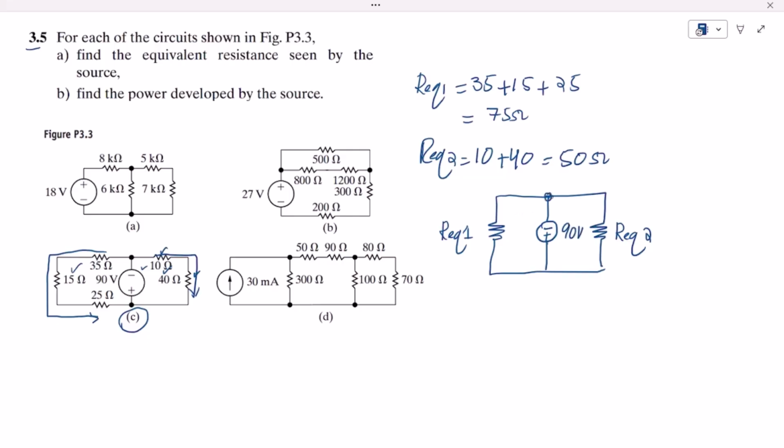Okay, you can see that these 2 points, these 2 points and these 2 points, let me change the color of them as well so that you can see them clearly. These points are shorted together, there is no other source or any other passive element here. Similarly, these 3 points are also in parallel.